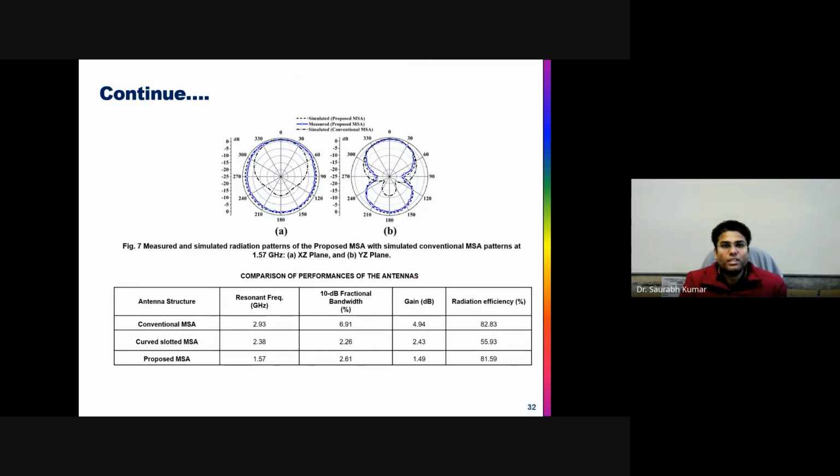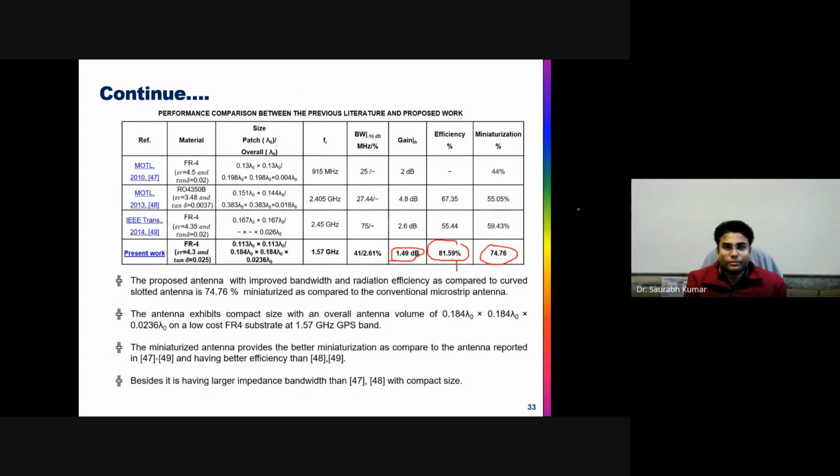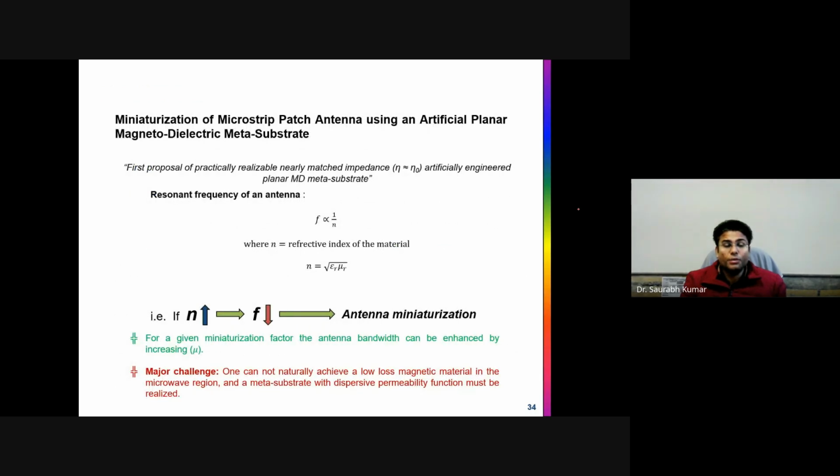So you will have the bidirectional radiation pattern. You can see the black one is the conventional antenna, conventional microstrip, and this is the back lobe of the conventional, a very small one, you can say. And now the EBG one has your monopole-type radiation pattern, a figure of 8 and a circle in the H plane. So these are some limitations.